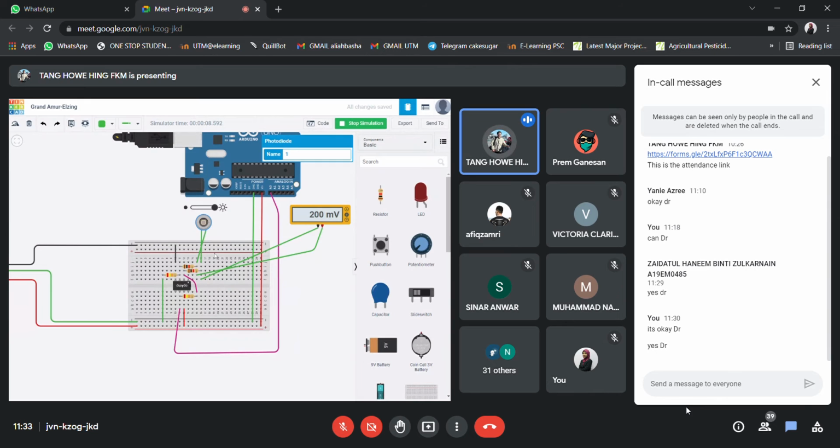Perhaps you may use a voltage follower to isolate the photodiode from these resistors. Most will use a voltage follower. Or what I'm doing here is actually increasing the resistance. Previously, the resistance I calculated was for a gain of 12.